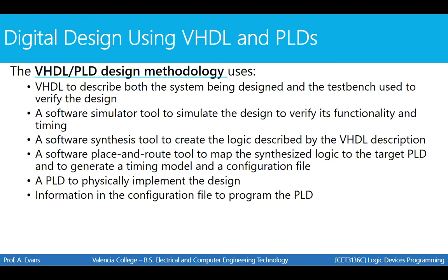The design methodology for VHDL also uses a software synthesis tool to create the logic described by the VHDL description. So we're going to be typing VHDL code into Quartus, and that software is going to perform synthesis, which is going to take our code and transform it into the logic that needs to be programmed onto the circuit board in order for that PLD to execute the function that we're trying to program. Quartus also is a software with a place and route tool to map the synthesized logic to the target PLD and to generate a timing model and a configuration file.